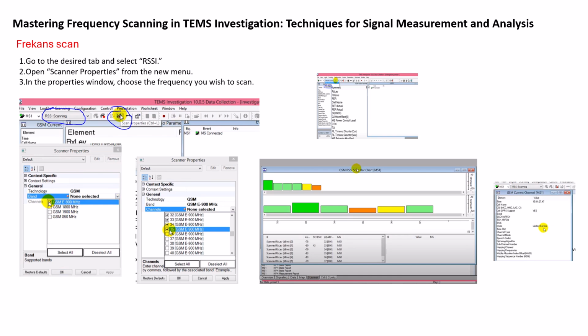Configuring a frequency scan. First, select scan mode or device. In the device or scan settings menu, choose a supported phone or scanning receiver capable of frequency scanning. Some devices may allow scanning only in certain bands, for example GSM 900 or LTE band.